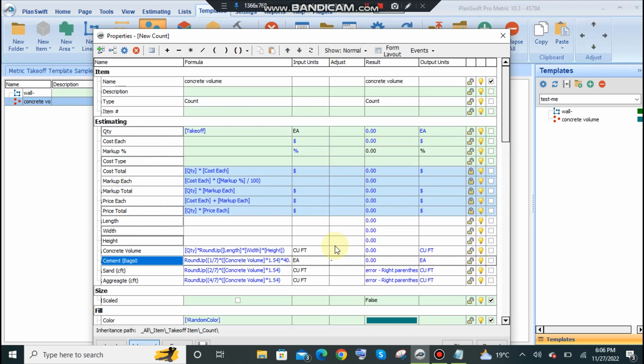We want to see unit as well of length and width, so check these to see unit as well. You can change unit every time, but feet will automatically be there. These units will automatically be seen every time. I want to see diameter as well, again in feet, and I want to see height and diameter in the same row. So check this option: length, width, dia and height. I don't want to see shape along with the height. So yes, this is okay for me. This is in organized manner. This is how our tab will look like during marking.